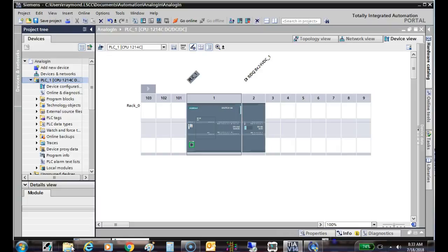So this is why meters are rated in counts. We have 2,000 count meters, we have 4,000 count meters, and we have 6,000 count meters. And you can see where it ranges. So a 2,000 count meter would range on 1999, right? So as soon as it got to 1999, then it would automatically do what? Range.